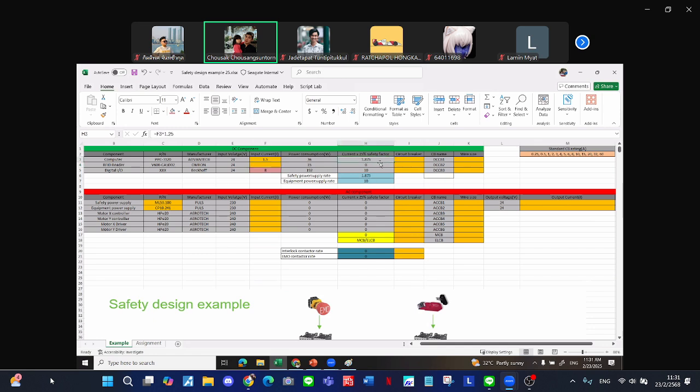We will use this value from these standard circuit breakers. This is a value you can buy in the market. I mean from the manufacturer, they don't have a specific number like this. We choose the closest one to this value. This one is supposed to be 2 ampere like this. And then we will use this value to find the cable size, the wire size.